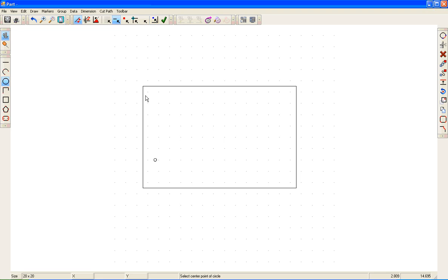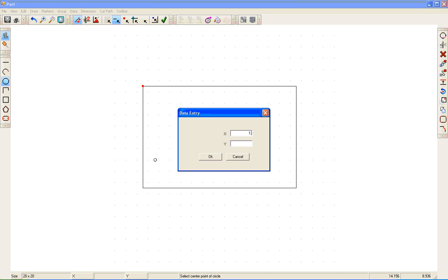If I want to place it from the next corner, you always need to hit the Set Reference Point button before you actually click the corner. So I'm going to select this corner. Again, I'm going to type 1 1/8 inch, but this time on my y-axis, I'm going to type negative 2.5 inches.